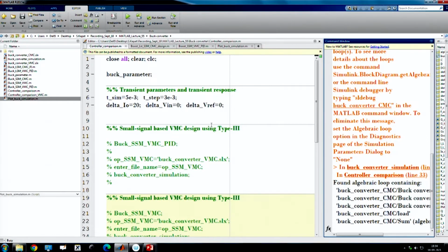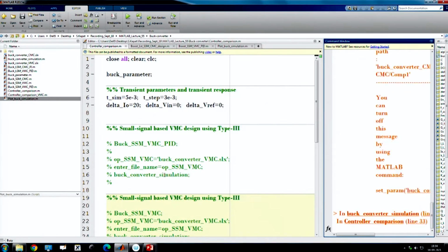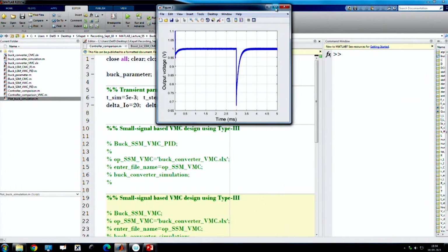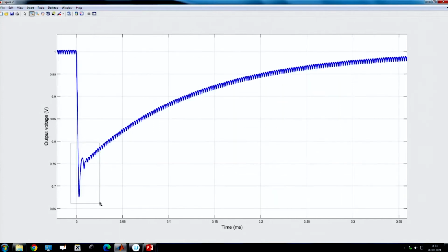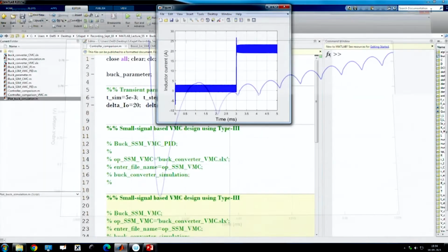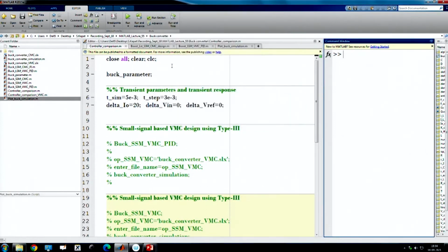This is a load transient response using current mode control, and you see, as we have discussed, the model matching will not happen due to the jump. So, we should not go to 1/5. Let us limit it to 1/8. That means we will get 500 by, let us say, 1/8.